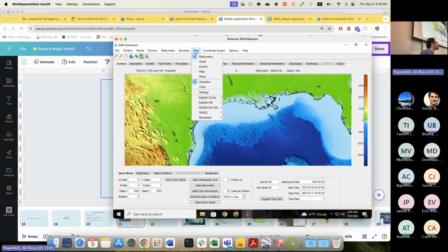Yes, there is a warning about overriding files that exist. Oh yeah, just click yes, because if you are in the middle of setting up a model, you shouldn't change your coordinate system. It will discard everything. We have not set up anything, so it's okay. Just click yes and continue. Should we use an empty directory or the one that we downloaded? Just make a folder for yourself. I personally made a folder called case one on the desktop, and I selected that as my working directory.